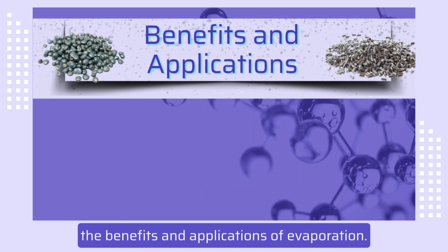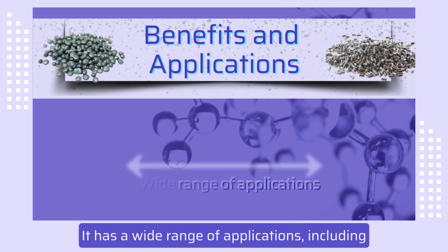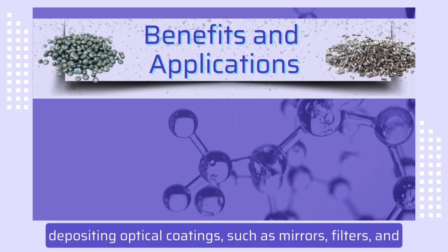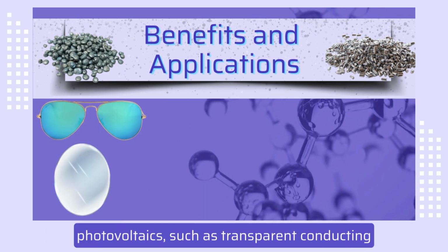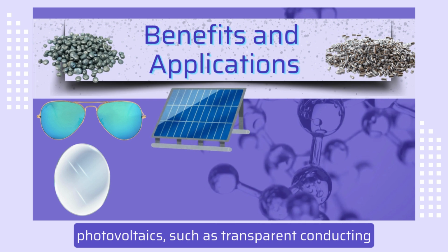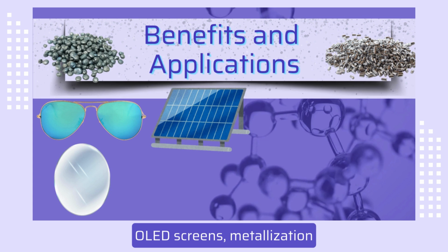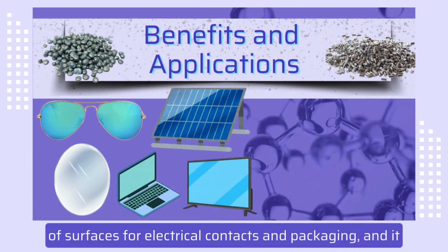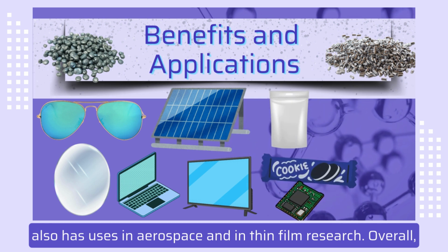So, the benefits and applications of evaporation: it has a wide range of applications, including depositing optical coatings such as mirrors, filters, and reflective coatings. It's used in photovoltaics such as transparent conducting oxides, thin film electronics such as OLED screens, and metallization of surfaces for electrical contacts and packaging. It also has uses in aerospace and in thin film research.